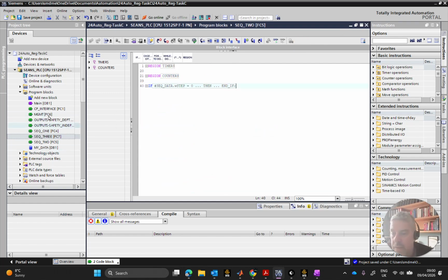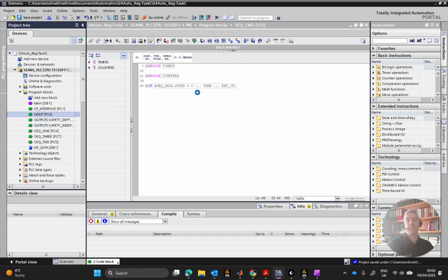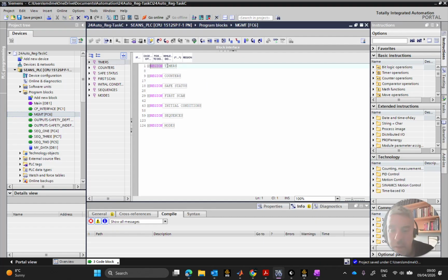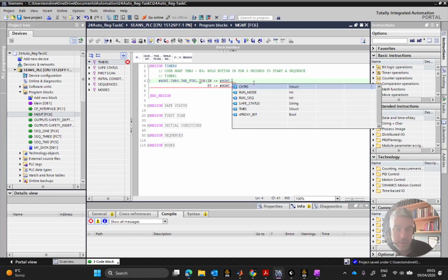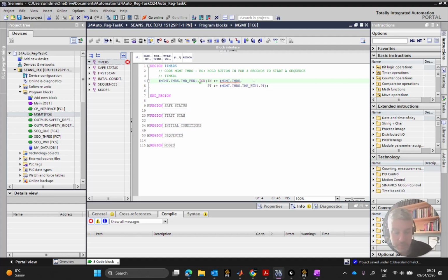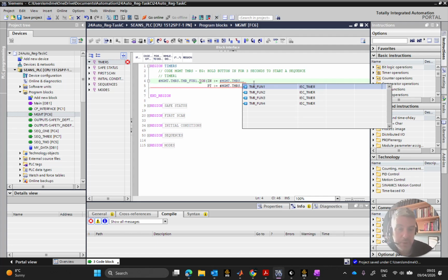Now the very last thing I need to code is my management. Right? So the timers, I have no counters in here. I'm just going to delete them out for convenience, but I do have timers. Actually, I have 3 timers. So management timer 1 function, so the proxy bit. So my first timer, the input here is going to be my management dot timers dot timer 1 function.